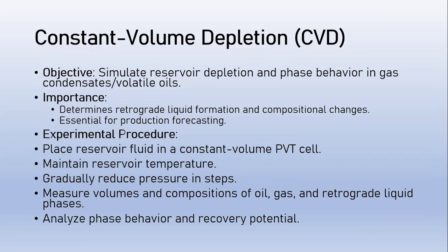The objective of this is to simulate the reservoir depletion and phase behavior in gas condensates or sometimes some volatile oils, which are near critical. The importance is to determine the retrograde liquid formation and compositional changes. It's also essential for us to have these results so as to build good models and also run production forecasts.